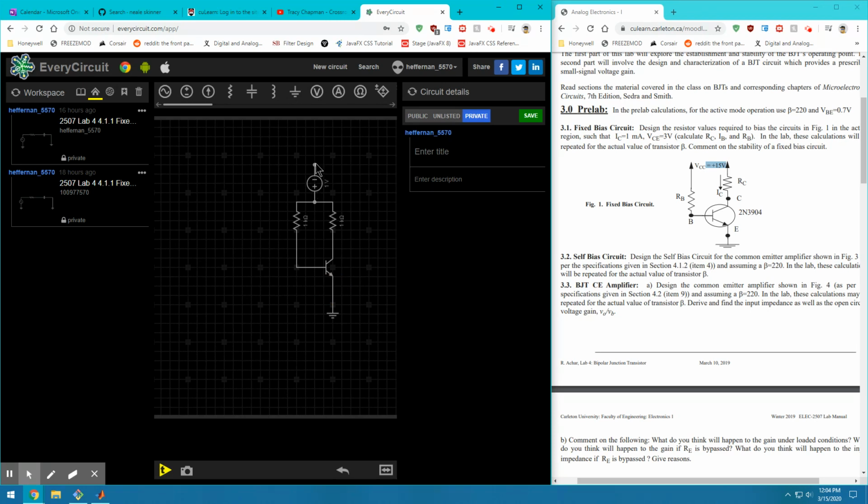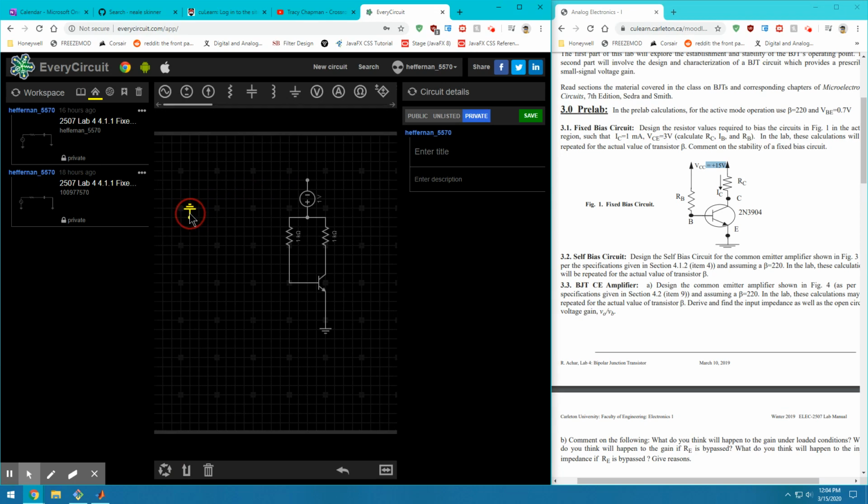All right, now last but not least, let's place a ground node on the back of your voltage source. For any simulation to run in this tool, you need to make sure all your circuits are grounded out properly. So let's go ahead and flip that again, and we'll place that on the back of right now our 1 volt source, but we're going to switch that right now using the adjust tab. So hit A for adjust, and you should be able to switch that to 15 volts. And you can use these little fine tuners here to get it a little closer to where you want it.